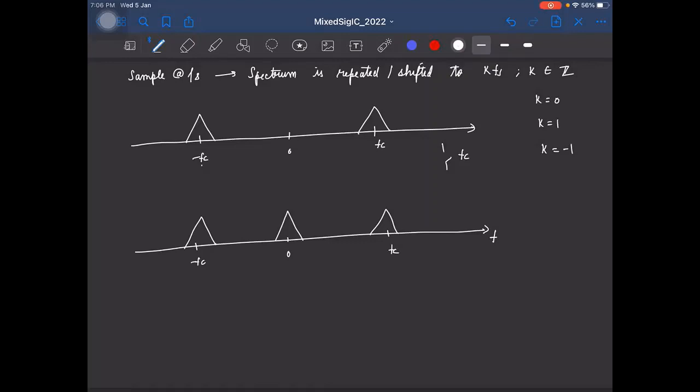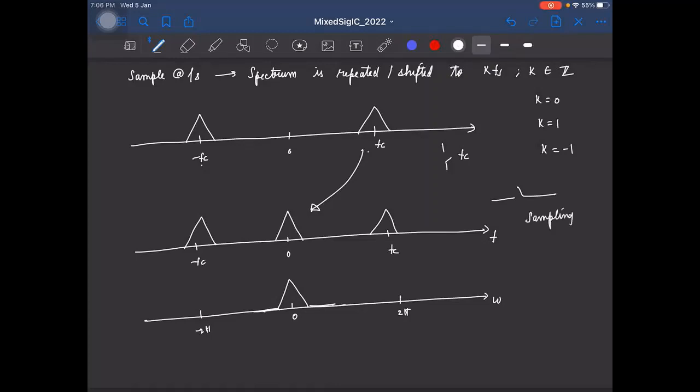Okay. So well, if now we have sampled it, in the discrete time, what will happen? The frequency axis will get scaled. This will be 2 pi, minus 2 pi. And we got back the signal, right? So we down converted the signal from Fc to DC, that is baseband, just by sampling it. Okay, and this sampling operation can help us to down convert signals. So this is also sometimes called sampling mixers, and a minor variant of it is also called a passive mixer.